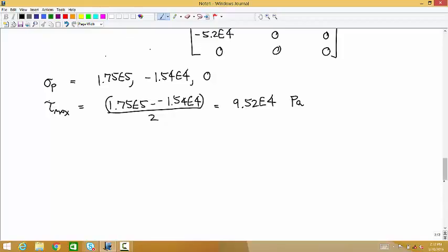It's like all this stuff just depends on certain assumptions, and the assumption here, I believe, is related to the fact that you're assuming that the shear stresses are vertical. If you're higher up on a circular cross section, they would be angled, tangent to the circular cross section, and so the assumption doesn't hold. And so we can only do it for the one spot on a circular cross section where the shear stresses are vertical.